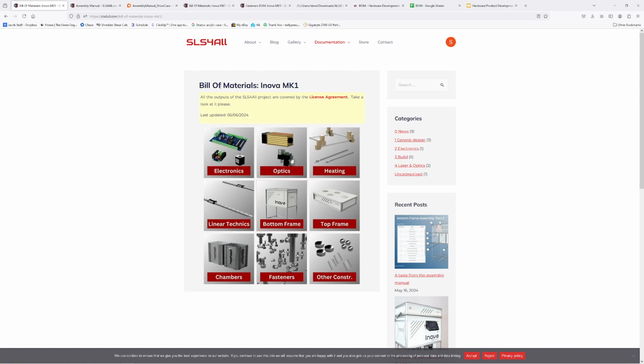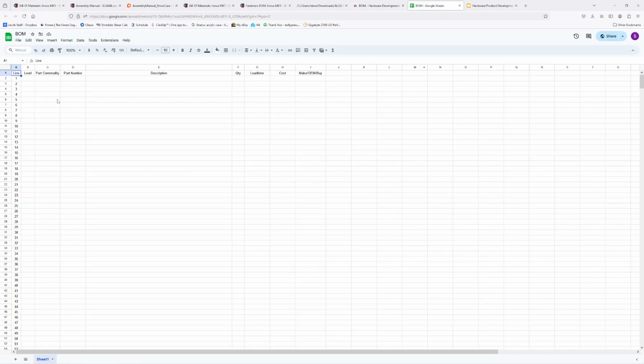So here is how he did his bill of materials. This is kind of how I suggest a bill of materials be done: you go through here and can see the different lines and the levels, and whether this is a parent or a child. Generally how it works is you'll have a kit. A kit will be like level 0, or first you would have a parent. So this would be the parent, and then you can say this is a Nova version 1.0.1 assembly, right? Or MLO, master layout, or assembly, or whatever.